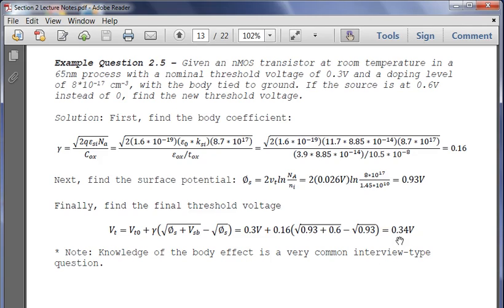So what we have to realize is that by using these body effects and using positive and negative body biasing, we can actually impact the power consumption beyond just what's done in frequency. So knowing this is actually important. It's kind of a confusing concept at first, particularly how to use these.